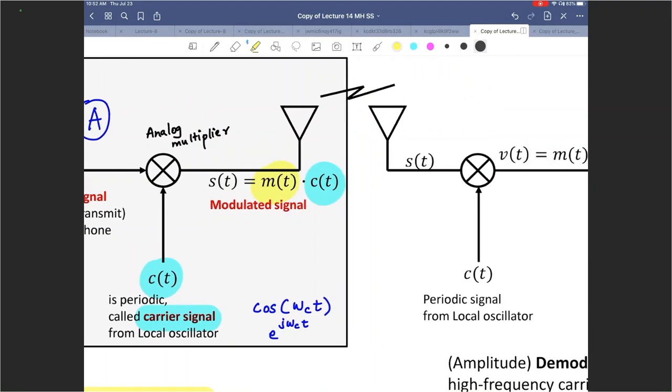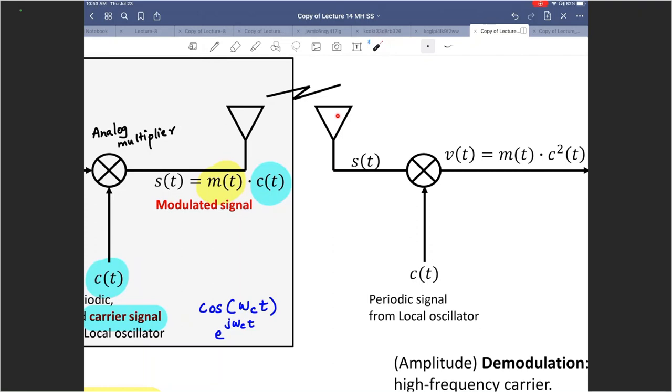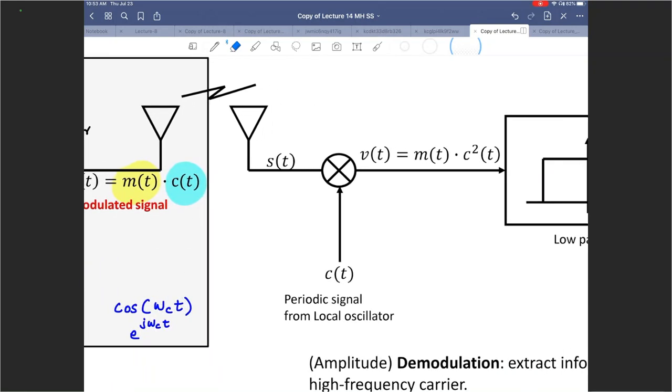Next, you use an antenna to transmit that signal, and then somewhere, close to point B, you have a receive antenna that is essentially tuned in such a way that it resonates with the frequencies of the carrier itself, so as to pick up those frequencies. So you have this receive antenna here. And if we did this in a perfect world, if you transmit S of t, you get S of t here. Practically, you might have some S hat of t. We are assuming right now that there was no change in the signal when you did the wireless transmission. Just for the purposes of discussion, we are assuming that whatever you transmit is what you receive here. And then you will have amplifiers here, you will have filters here, you will have a bunch of components that will make up your receiver. But we are just showing the absolutely important aspects.